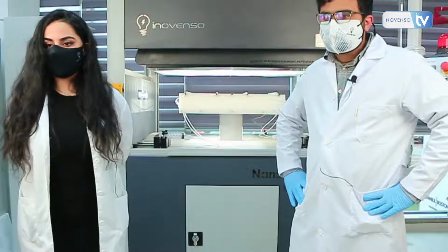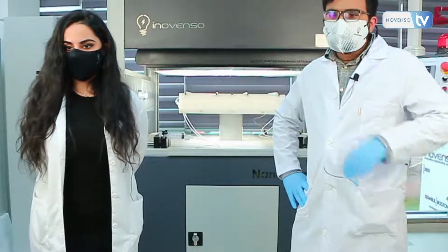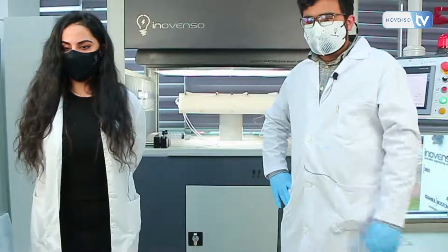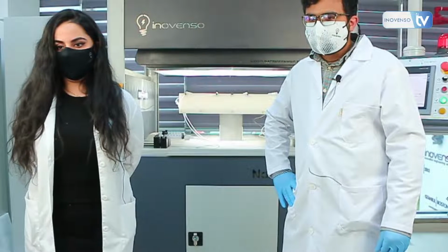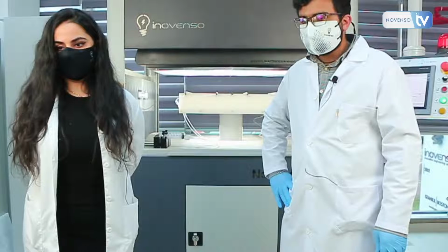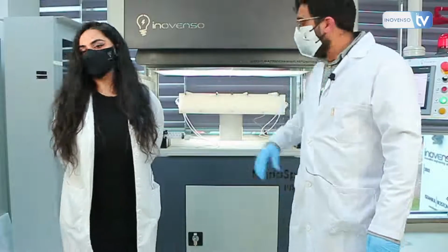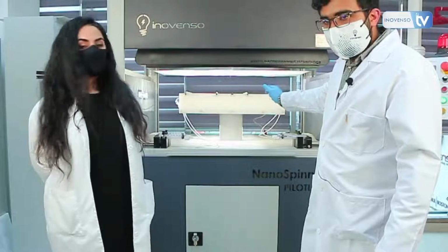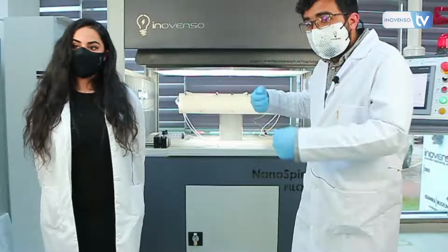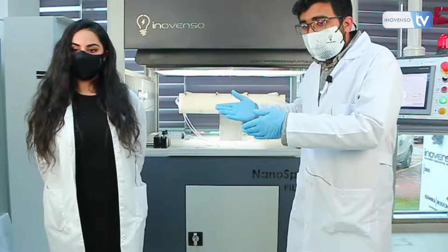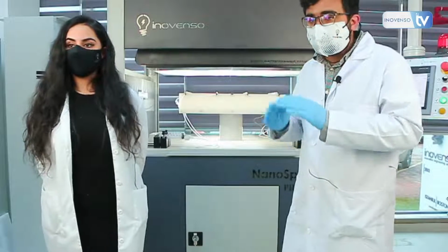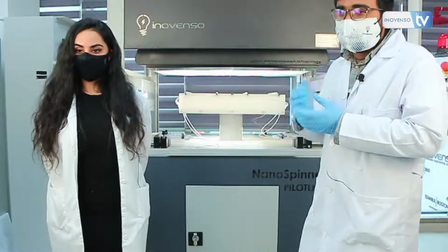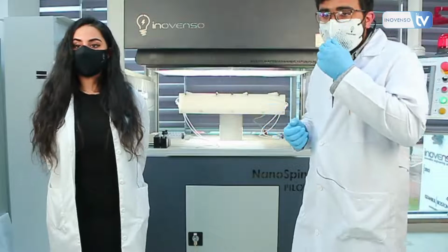We have another question. Can we please come up a bit? Can we see the questions? Yes, please. Thank you. Are the nozzles automatically earthed after the machine is switched off? Yes, so our machine has a grounding outlet at the back. It needs to be externally connected, and once it's connected and the machine is on, within a few seconds, it gets earthed properly, and you just need to activate the high voltage, and everything is good to go then.